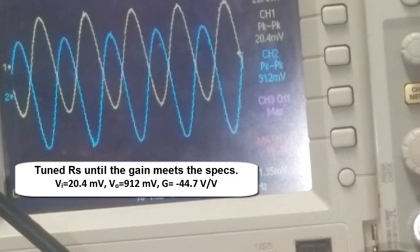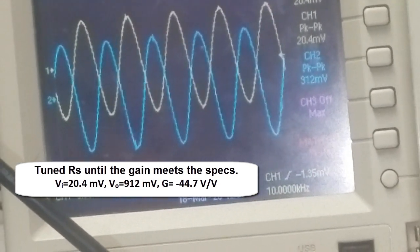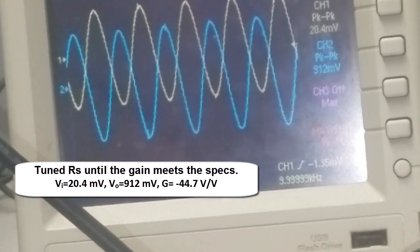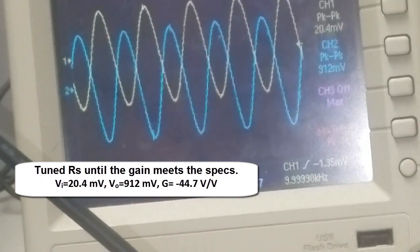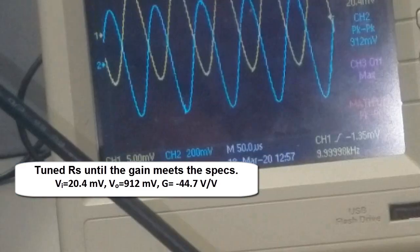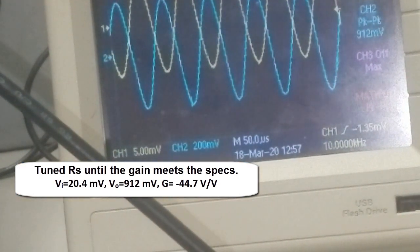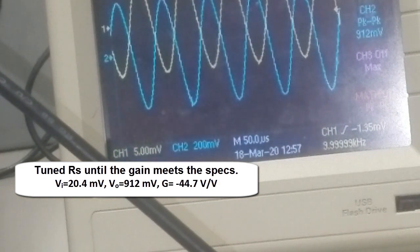You can see that channel 1 is 20.4 millivolts and channel 2 is 912 millivolts. Channel 2 is the output, the blue line, and channel 1 is the input, the yellow line. So clearly we meet the specs, because the specs say the gain should be between 40 and 60, nominal 50. We got a gain of 44.5 volts per volt.